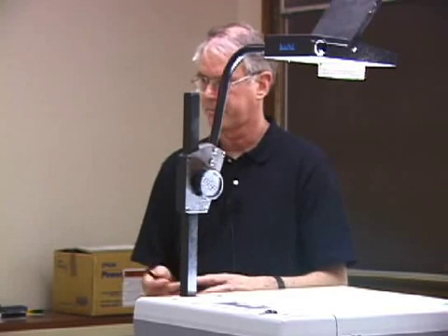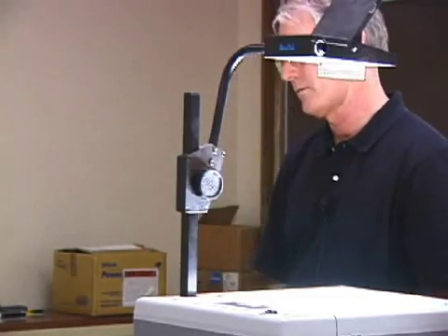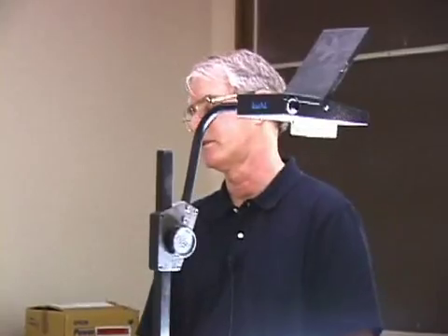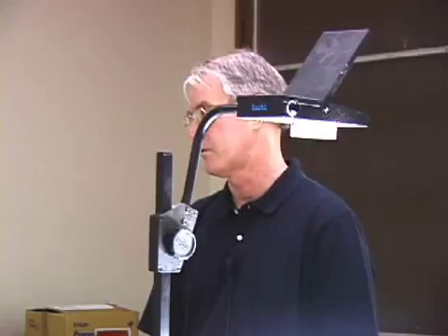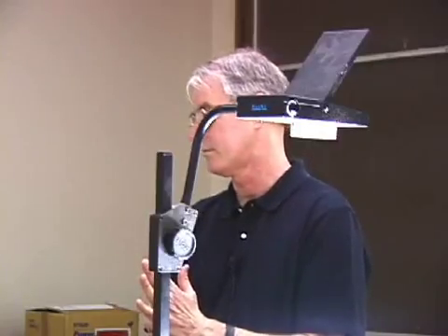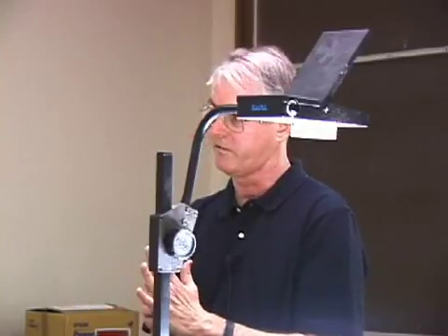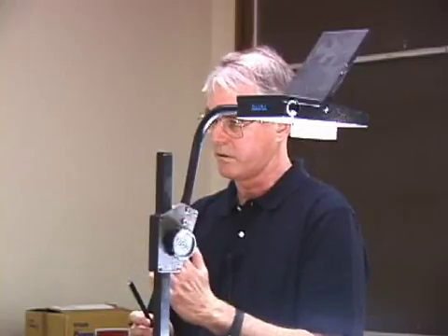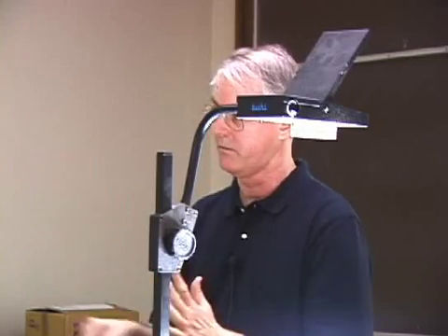And quantization noise is not a problem? Well, quantization, I mean, you can buy 24-bit audio A to D converters that are very good, operating at a kilohertz. So if you want 1 hertz, going from 24 bits at a kilohertz to say 30 bits at a hertz, I would think that would not fundamentally be a problem. I'm worried a little bit more about matching the gains of these A to D converters around the network, around the array of data. I think that's a problem that needs to be looked at.